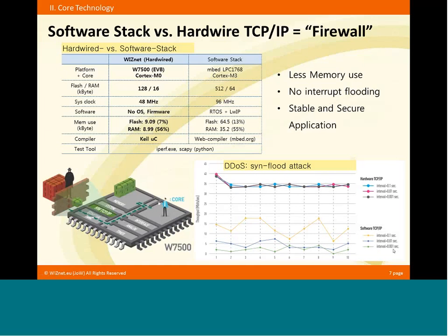So this is in a standard LAN network where someone makes a file transfer from one PC to another PC, and you have those embedded applications attached to the same network. The MCU is totally occupied, and the network performance drops totally. So you have to take care which traffic goes really on the interface. That is what we call a firewall function by the hardwired TCP/IP core.